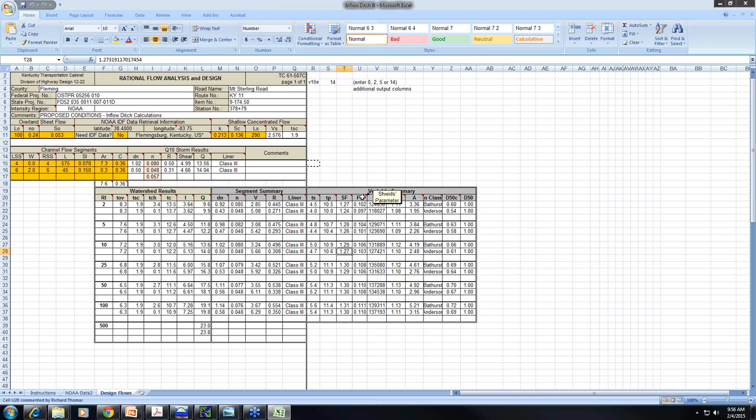That safety factor was 1.27. The Shields parameter adjustment from 0.047 was adjusted all the way up to 0.103. Here's the particle Reynolds number, and you can see it's not quite up to 200,000, so it's not up to the 0.15 Shields parameter adjustment yet.